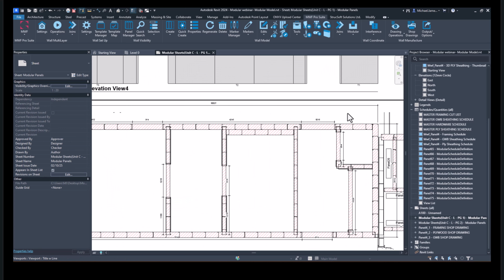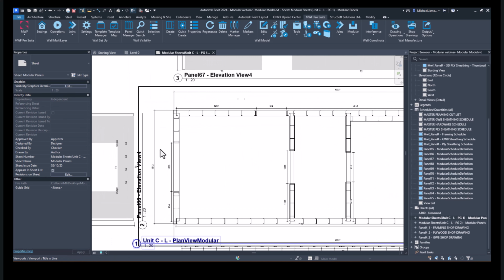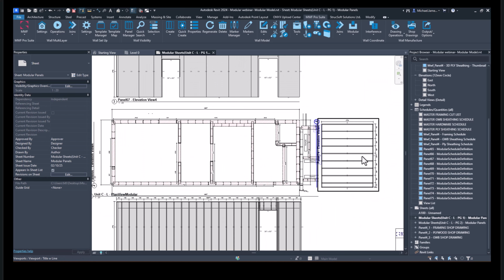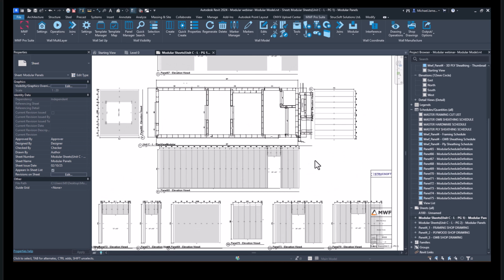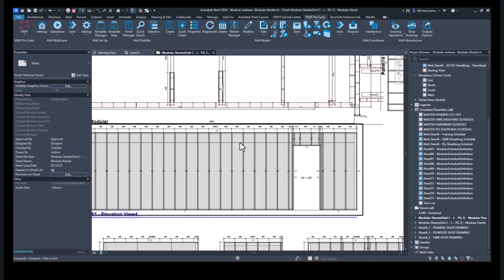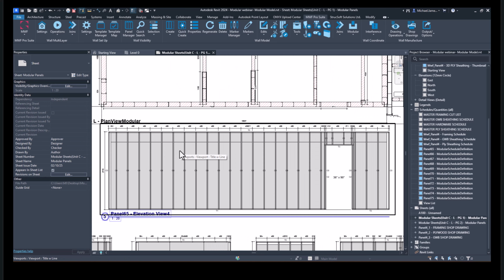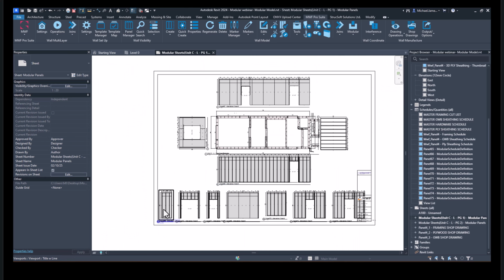So we've got the overall length of our unit, overall width of the unit, and then we have just a structural panel here without the sheathing boards, as this one may not have sheathing on it anyway. So we can show our panels in different ways. In this case, you can see based on the orientation of this panel, we are seeing the structural members in front of the sheathing boards. At the bottom, these are our interior walls. So here we have our exterior walls that make up the exterior of our modular unit, and then we have the interior wall panels which are placed throughout the unit.